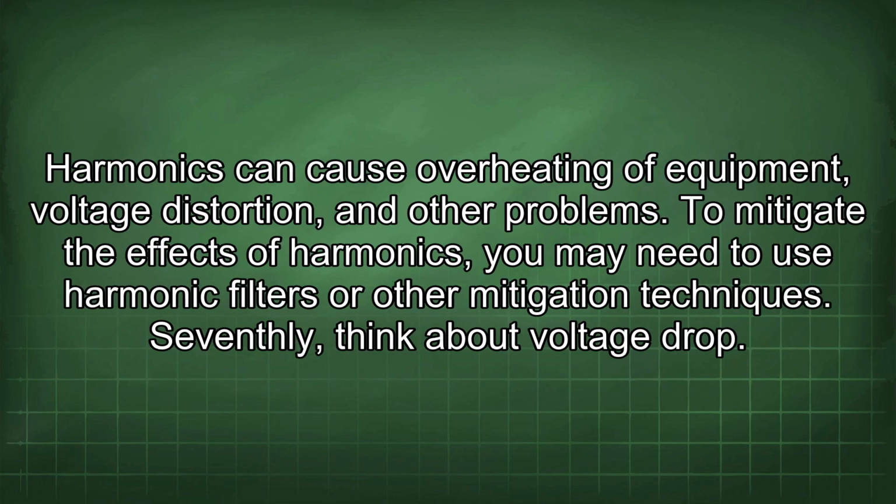Harmonics can cause overheating of equipment, voltage distortion, and other problems. To mitigate the effects of harmonics, you may need to use harmonic filters or other mitigation techniques.